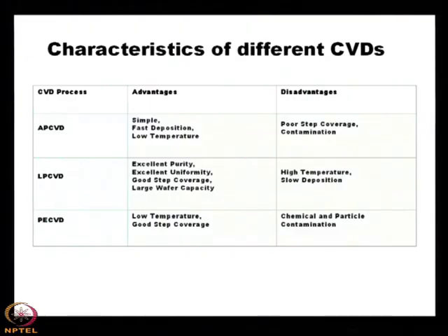For PECVD, the energy is additionally supplied by the plasma. So, that is why it is known as plasma enhanced chemical vapor deposition. Here you see that the temperature is low and there is good step coverage.